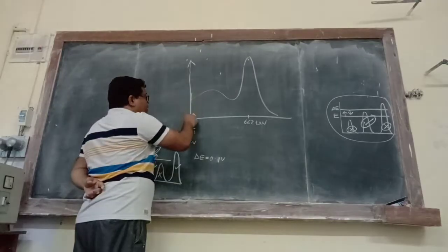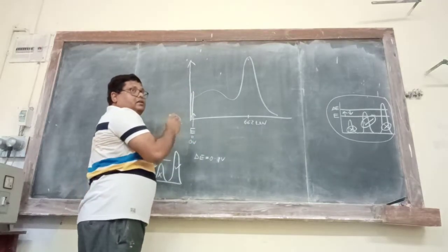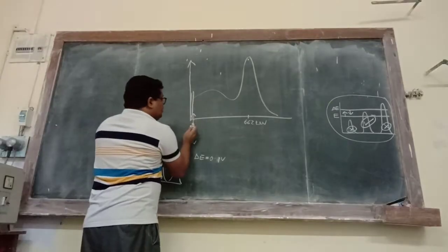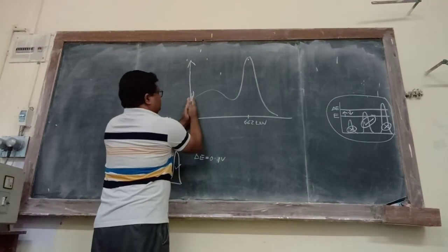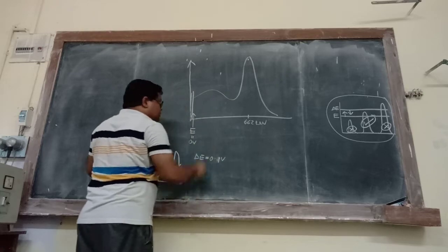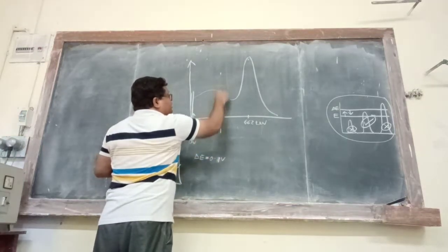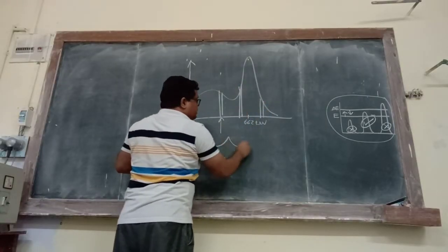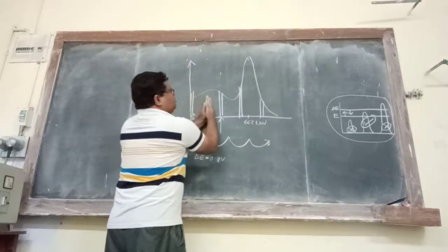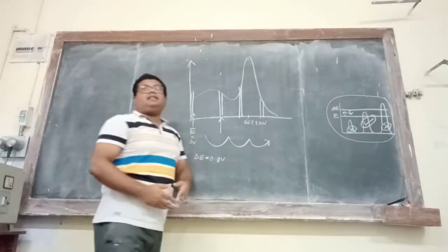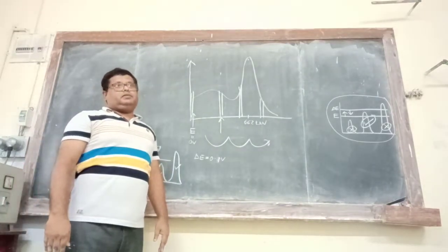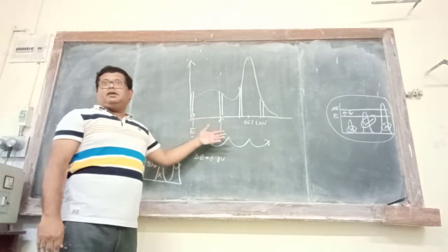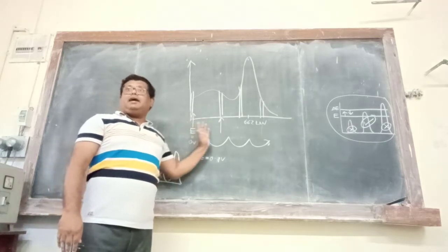Say we start with E equal to 0 volt. Then what does this mean? I am choosing an energy bin like this. Remember, volt here means energy actually. Then slowly I will be shifting this window. After some time, I will put the energy bin over here, and delta E will be fixed. After some time, the energy bin will be here, and here. So I will be moving forward like this. This is the way I am going to scan the entire spectrum, and this is how, using the single channel analyzer, I am going to record the entire spectrum.